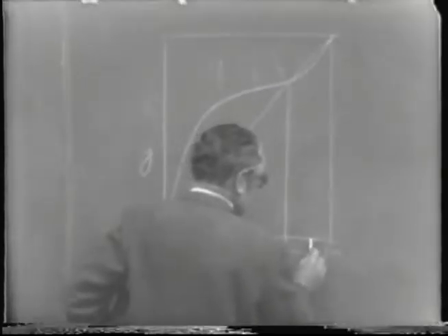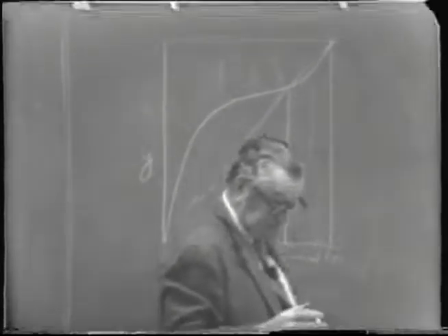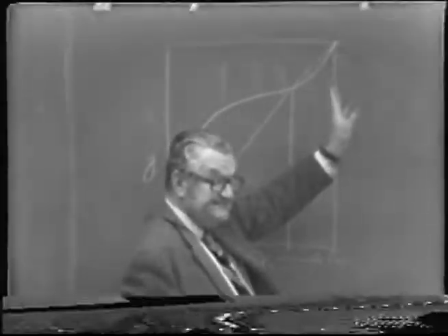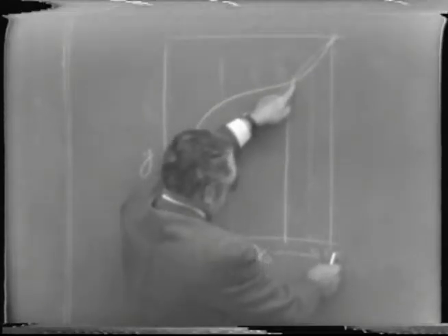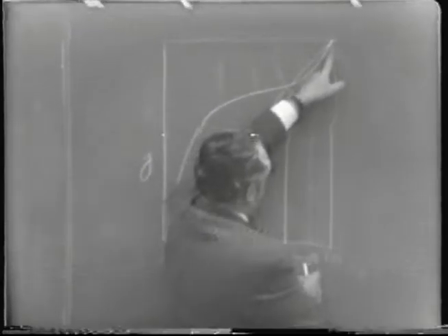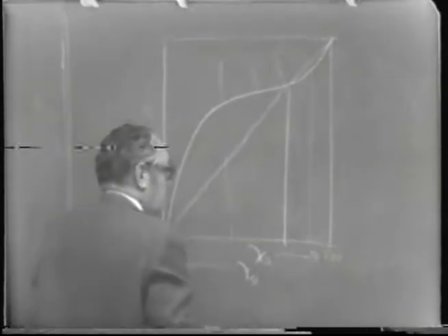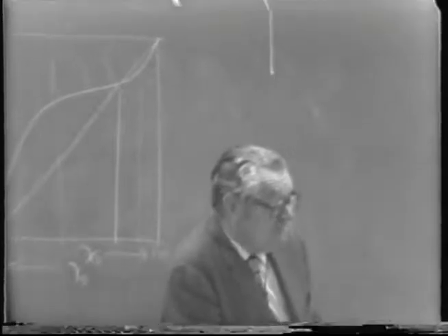And similarly, if you feed a mixture of this composition into a distilling column capable of affecting good separation, what would you get then? You get the material that's more volatile as a top product, and that is the azeotrope, and the bottom product would be pure X of A, or in other words, alcohol in this particular case we're talking about, because it's less volatile than the azeotrope.